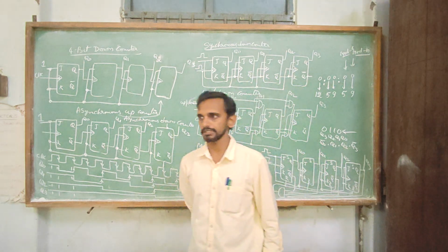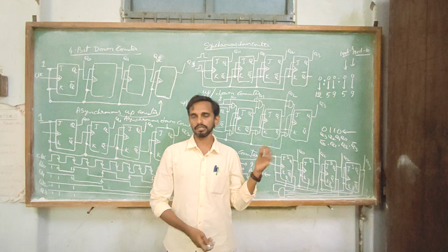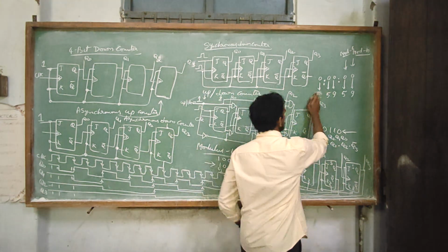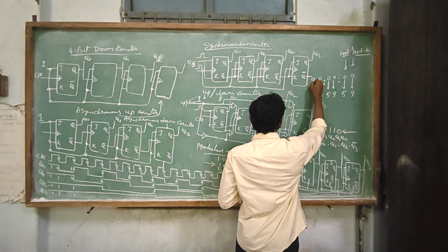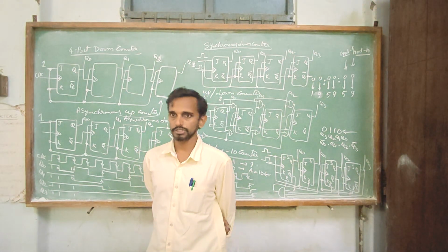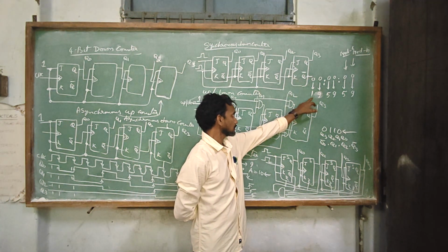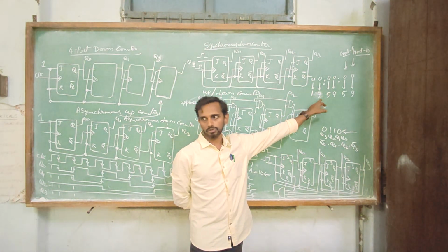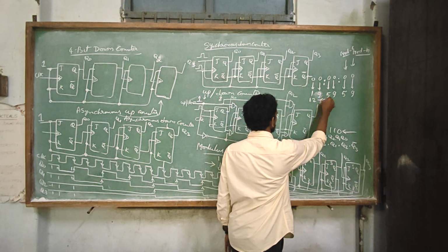So we have to use BCD. After counting 9, the counter has to reset to 0 and it should display 10. So here you need a 0 to 9 decade counter, followed by 0 to 1. But you require a special case that when this second digit is 1, the first counter has to go up to 2. After counting 12, it has to reset to 0, 0.